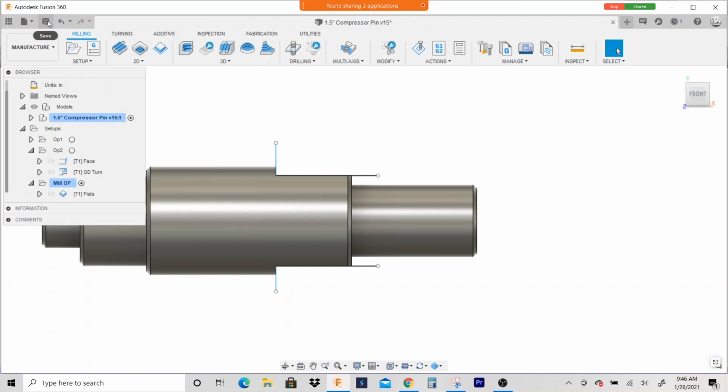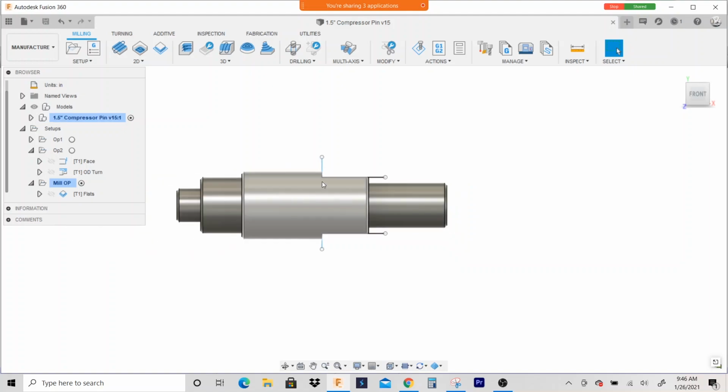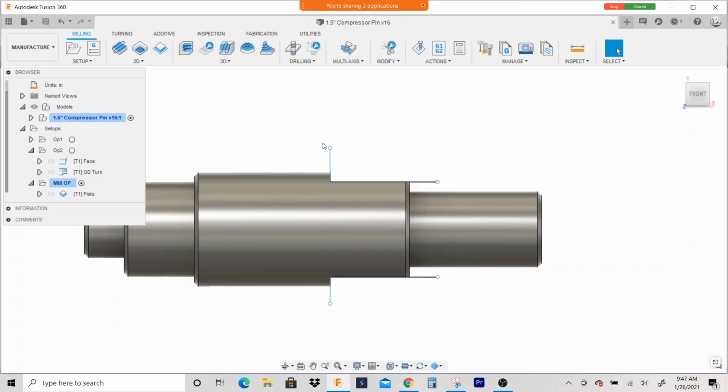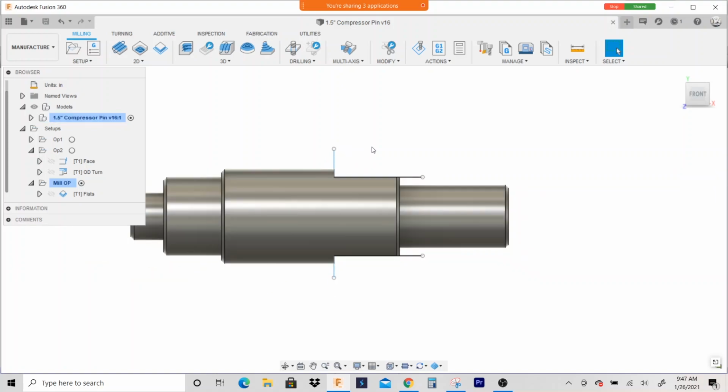But climb milling is better. You get better cuts. The end mill just performs better. And you're probably wondering, if climb milling cuts better, why do they even have conventional milling? That brings us back to different machines, like manual. With climb milling, the cutter basically removes the shavings away from the cutting zone as the end mill feeds in, and it kind of climbs up the part. In conventional milling, it doesn't do that.